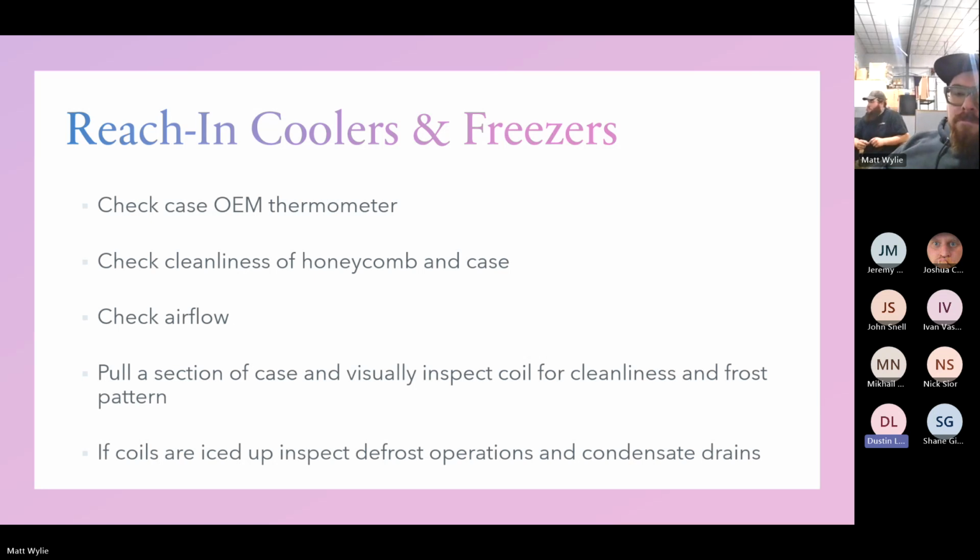The other side of it is extra moisture can cause ice buildup. So if your ice is gone after 20 minutes and your termination Klixon hasn't kicked it back into refrigeration and the time clock is set for an hour and a half, well, guess what? It's going to start getting steamy in there because your time clock's not going to kick it out. So it's not always just the time clock.